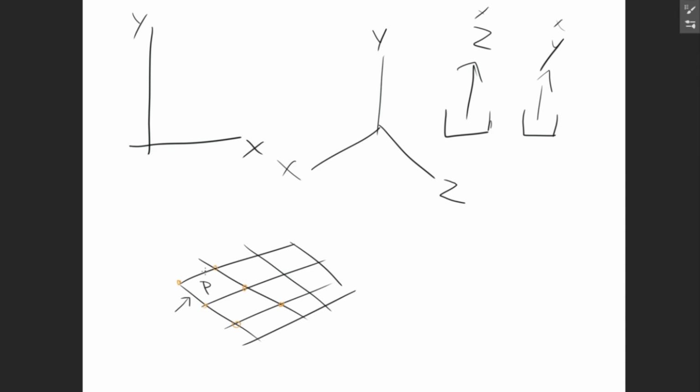When you're talking about assets for game engines, real-time rendering engines, usually what they do is calculate the amount of vertices. So what you need to take into account is the amount of vertices that you're going to have for your assets. That's why the triangle count, or the vertex count if you prefer, is so important, because this is what's going to tell you the amount of performance that you're going to get depending on what kind of hardware you have. That's why it's so important to know about the vertices and the polygons of your model.